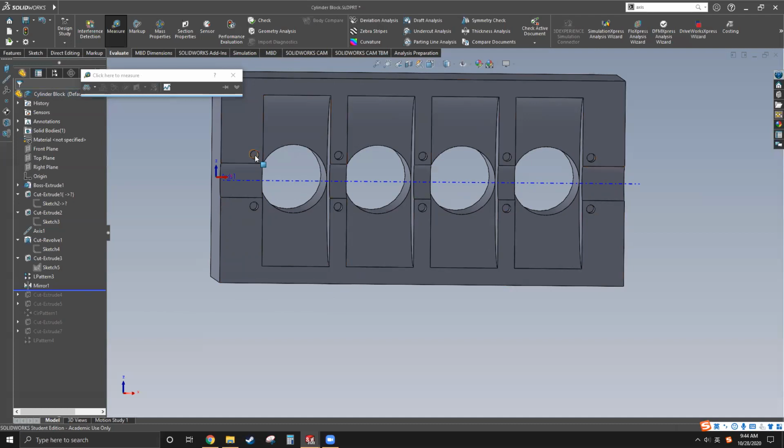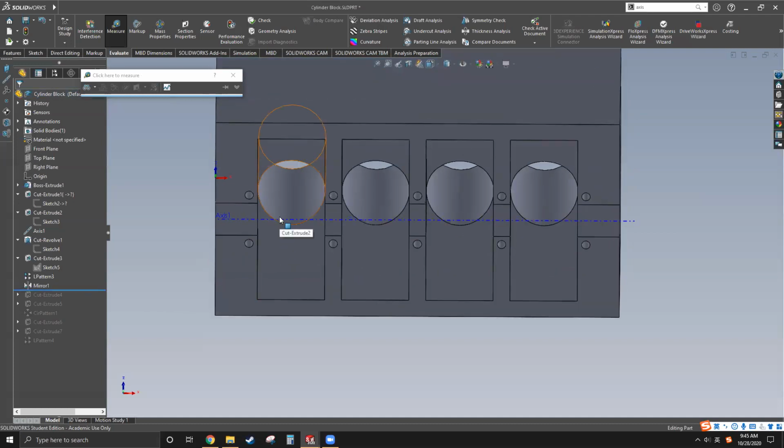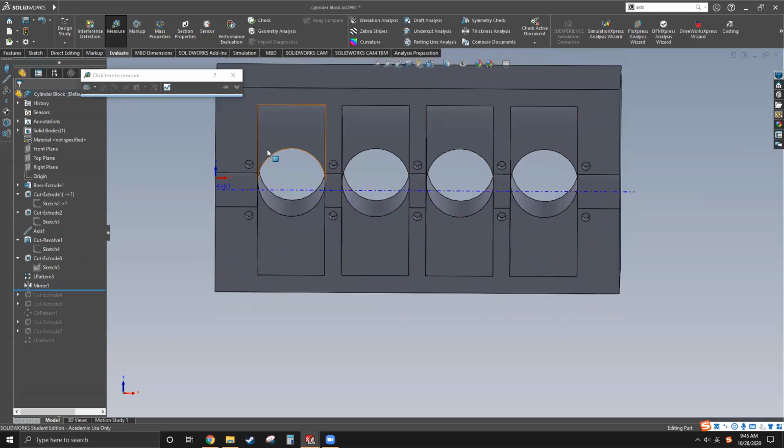All right, mirror these holes, all 5 holes, with respect to the mid plane you just created. So the same mid plane, you create your rectangles for 4 and use that to mirror all these 5 holes so you can make another set of 5 holes on the other side.